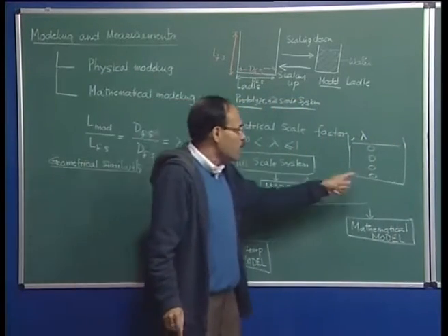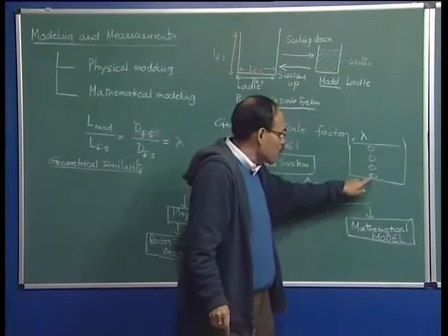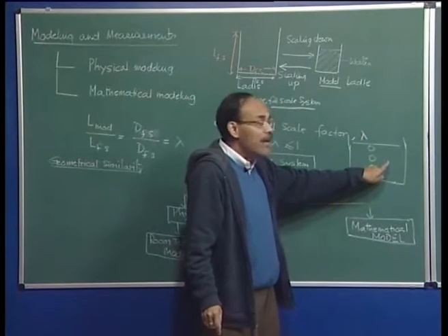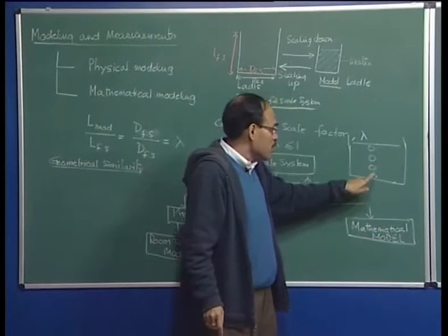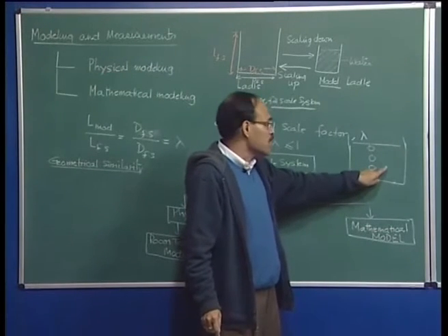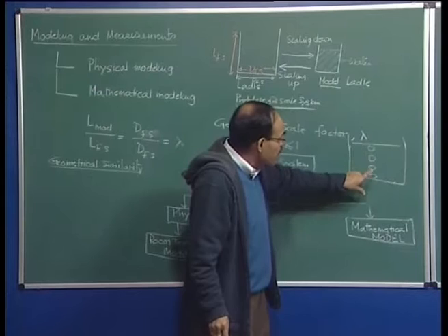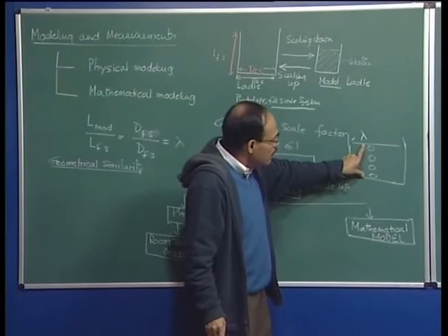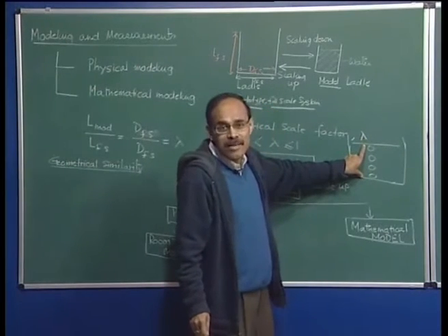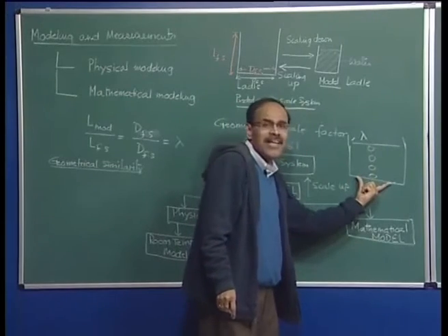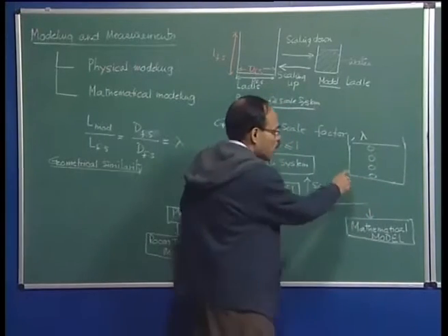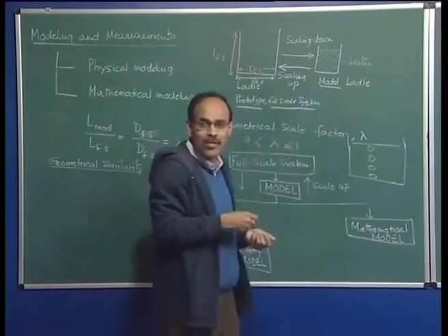Now, the rise velocity will depend, of course, on the inclusion material. The rise velocity will depend on the bulk density. The rise velocity will depend on the viscosity. It will depend on how much time it is going to take, and will also depend on the depth of the liquid in the system. The diameter of the vessel has really no role to play as far as the rise behavior of the inclusion is concerned.